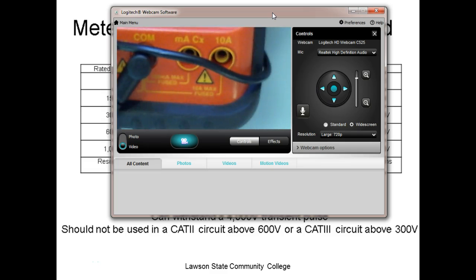But why can it do that? Because it's at such a high voltage. So you get into these big motors. I think somebody told me US Steel has some motors that run off 6,600 volts. You get into 6,600 volts with the wrong meter and you create a little arc, then you got problems. But as long as you take care of yourself, and that's why if you get into a voltage like that, you're going to go in with your bomb suit on. Right. Basically it's a bomb suit. I mean, it's insulated, it's got padding, you got your helmet on, it's sealed up on the bottom.